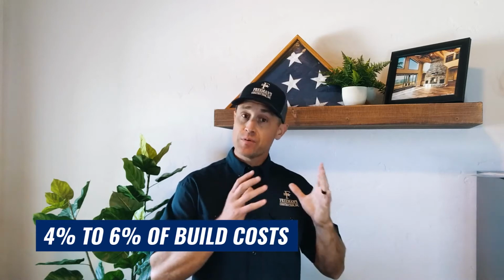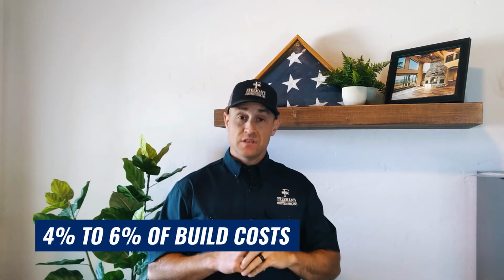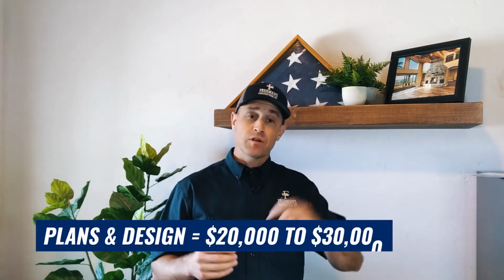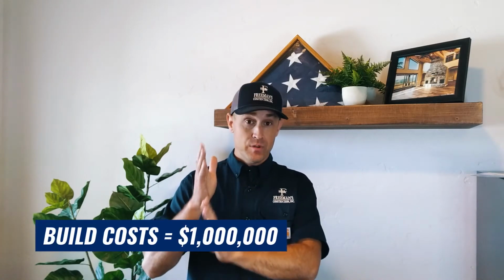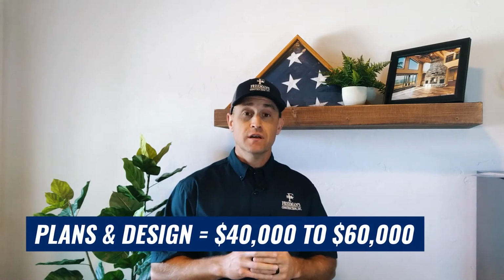Now, what does this all cost to do? Typically, you're going to spend somewhere between 4% to 6% of the actual build costs to get the plans and design completed. For example, if you have a $500,000 build cost budget, the plans and design would cost somewhere between $20,000 and $30,000 to get that package put together. If we had a $1 million build cost, then we'd be looking at somewhere between $40,000 and $60,000 to get that package put together.